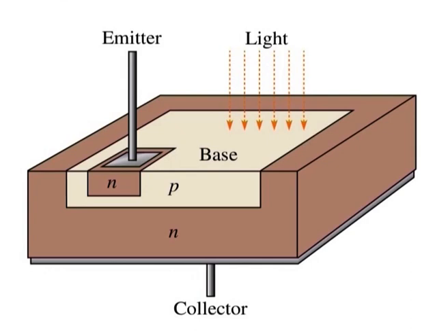The phototransistor. In a phototransistor, the base current is produced when light strikes the photosensitive semiconductor base region. The collector-base p-n junction is exposed to incident light through a lens opening in the transistor package.